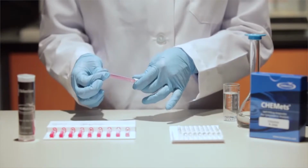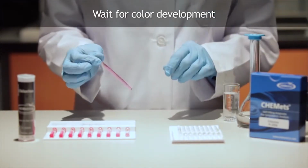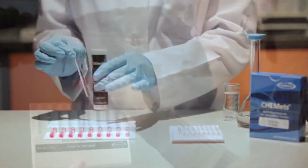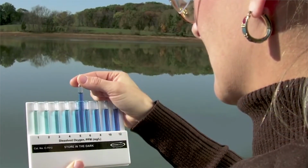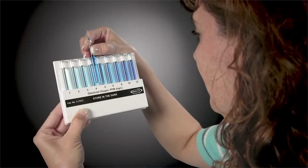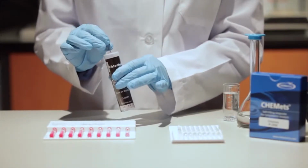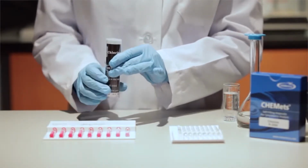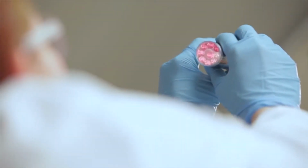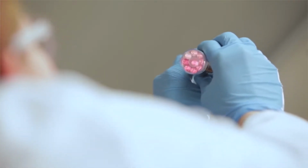Dry the ampule. The sample will react with the reagent to form a color. Reaction times will vary by method. Match the intensity of this color to the standards in the appropriate color comparator to obtain quick quantitative test results for your sample. For lower concentrations, use the round comparator by placing the ampule into the center tube. Direct the top of the comparator up toward a source of light while viewing from the bottom. Rotate the comparator until the color standard below the ampule shows the closest match.